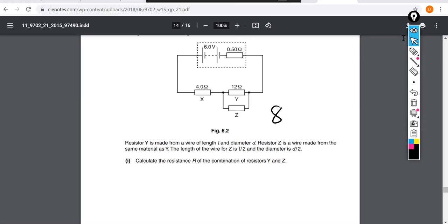So if we've opened up more paths for electrons to flow through, or we just think about it like, well, this part right here is now 8, then we have 8 plus 4, 12 and a half. Instead of 16 and a half, we only have 12 and a half ohms of circuit resistance, right? And so that's less than the 16 and a half we had before. So if we're less resistant to the flow of charge, we're going to draw more charge from the battery. The whole circuit is going to draw more charge now.